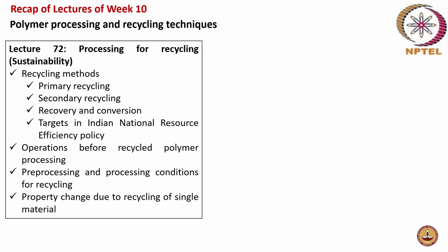For example, there was a discussion on decrease in molecular weight of PET and decrease in impact strength of PET, which can be due to contaminations like acids producing contaminants like polyvinyl acetate or polyvinyl chloride. And then how there's a color change in case of HIPS, high impact polystyrene. The color changes from white to yellow, and similarly, there's a drop in impact strength as well.